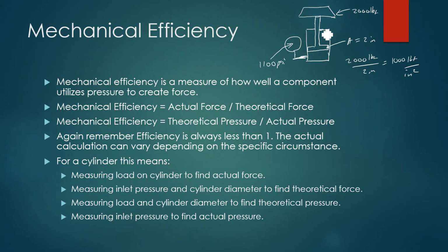Remember, a cylinder has got seals everywhere, okay, lots of places. You have seals around the piston, so there's seals here. There's piston seals. There's wipers. There's seals at the where the rod exits. If there's two rods on it, if there's a rod coming out the other end, you've got seals over here, right? So everywhere there's a seal, that's a great thing because it increases your volumetric efficiency.